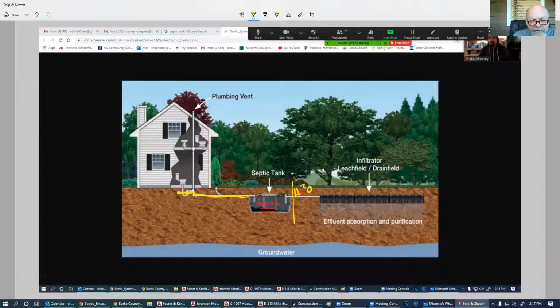And in order to keep this full of water, when we flush this, we need to have air that can flow up and down through this plumbing vent. As water gets put in here, the water level may rise, and we're going to expel air out through the vent. We definitely don't want to expel air through here. I mean, you know what it smells like when Uncle Henry comes out through there and uses your bathroom. You don't want to have Uncle Henry's 30-day-old crap out here stinking up the house.